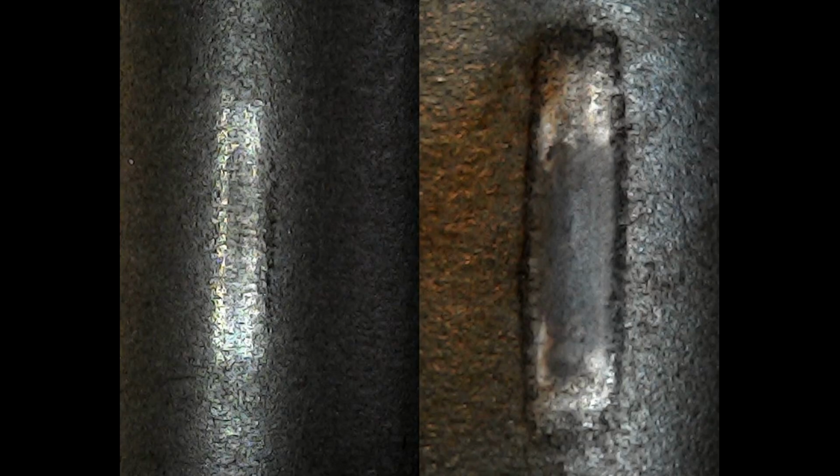Reducing the stroke amplitude to 1mm allows us to run fretting tests. In this case, we're looking at 2 different greases running at 10 Hz and a total stroke of 2mm. The tests were run at 0.75 gigapascals for 200,000 reciprocating cycles, generating 400,000 fatigue cycles.